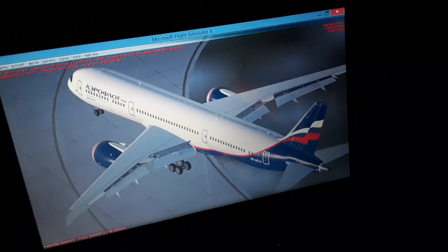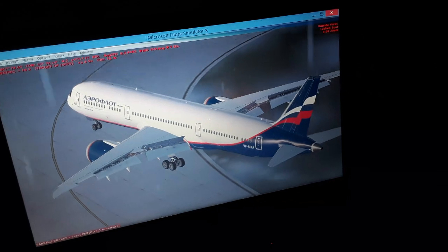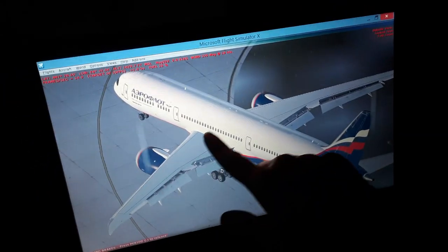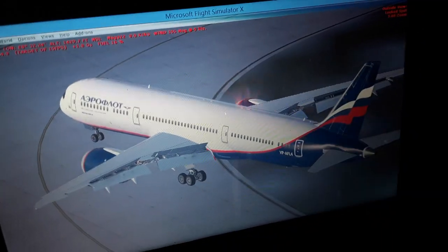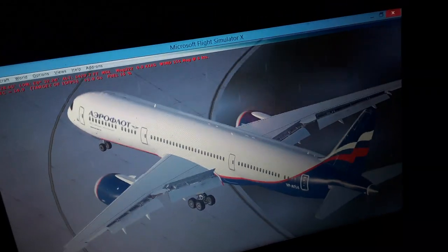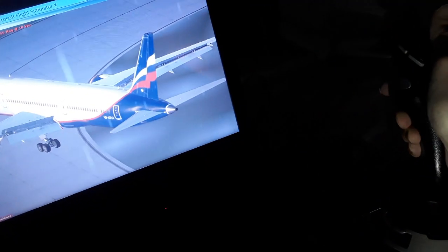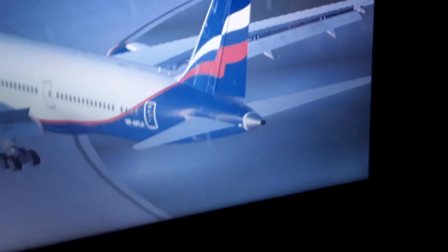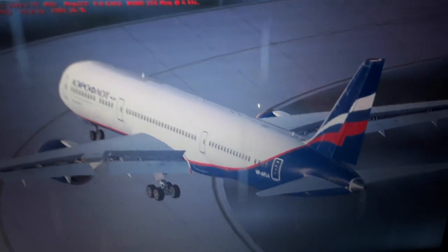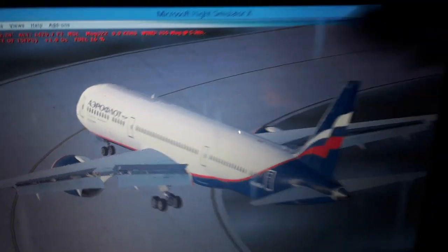We have all these things over here. We have the center of gravity, we have the fuel tank, the center fuel tank, and the left wing and the right wing's fuel tank, where the center of gravity is located. Pretty much here is where the yawing axis of the aircraft is located. We can turn the aircraft left and right using the rudder in flight. So we have directional control over here, as you can see, through the center of gravity axis, the vertical axis.